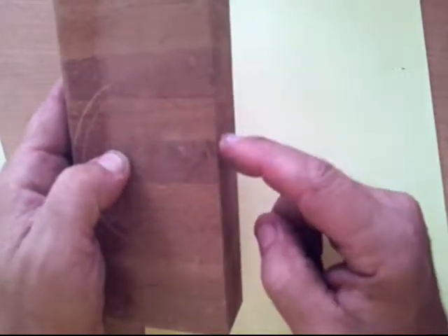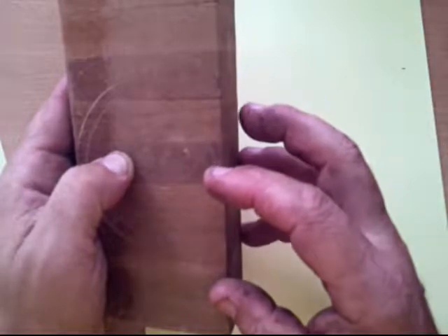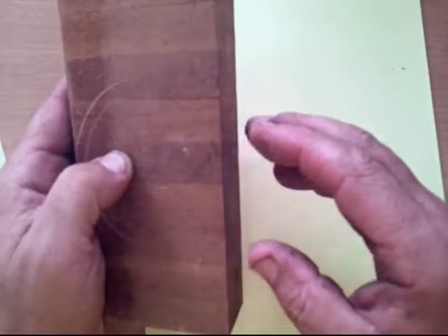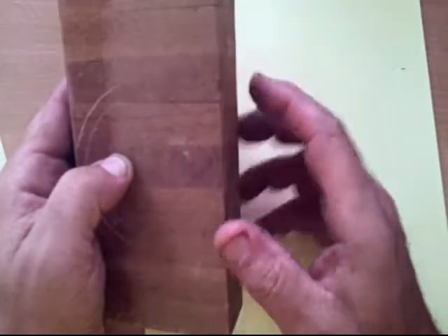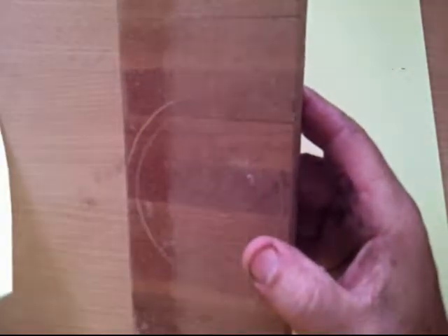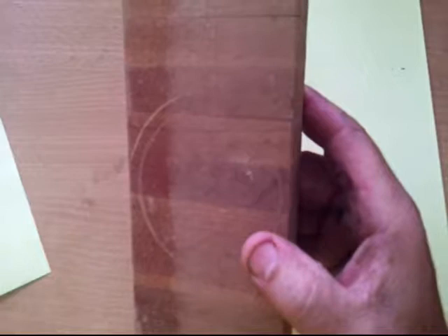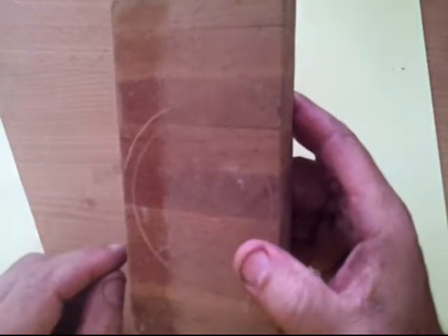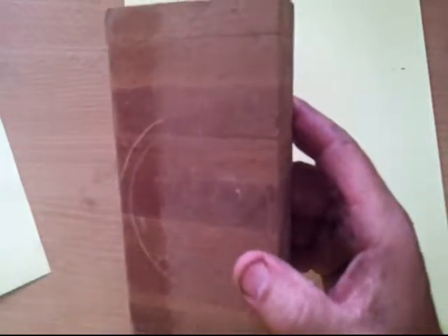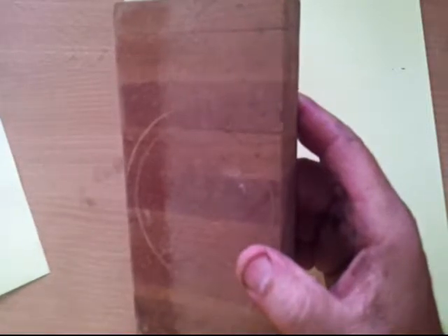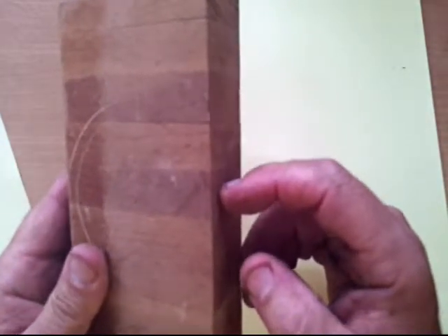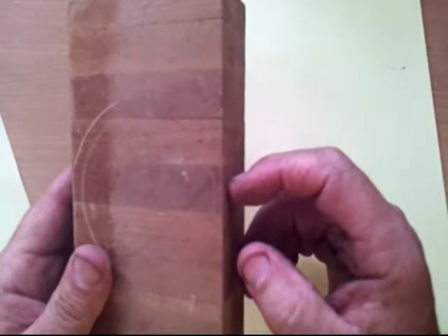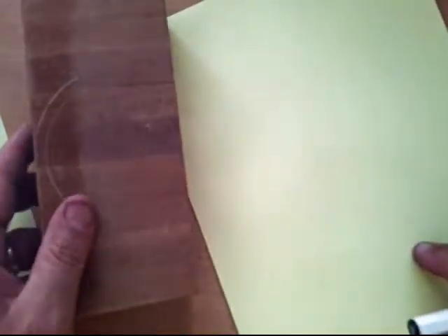with a glue, usually a very strong brittle glue like urea formaldehyde would be used rather than PVA, polyvinyl acetate, which is water soluble and will eventually creep over time. It's more elastic. Urea formaldehyde is a thermosetting plastic and won't loosen up again with water or with changes in temperature. Okay, so this has been laminated for centuries.